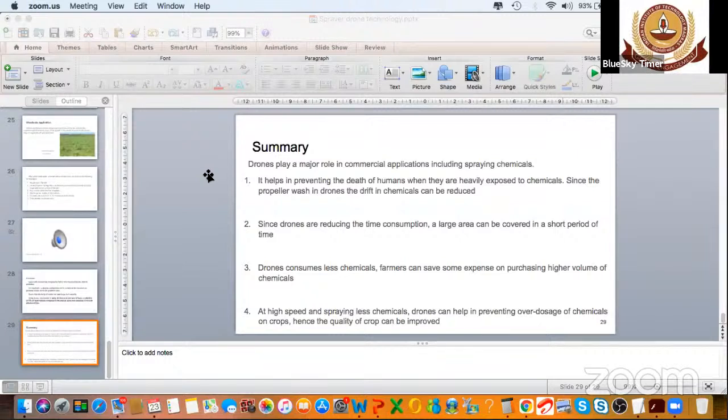The other thing that we have been working on very seriously is obstacle avoidance. Many times you will find there are poles planted in the middle of the farm, or you may have a big tree, or a well, right? Those obstacles come in the way. And when you have these booms, the drone needs to have situational awareness of how much its swath is, and it should not go and hit a pole. This is very difficult even for a human pilot to negotiate. So these things will require more automation that is specific to the situation. Those developments are required for us to make sure it's more and more crash proof.